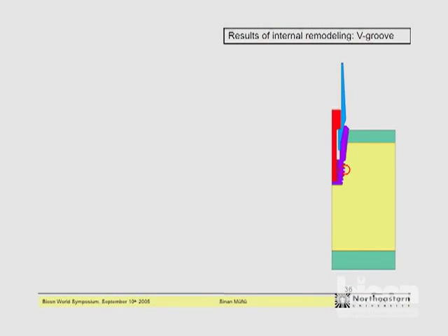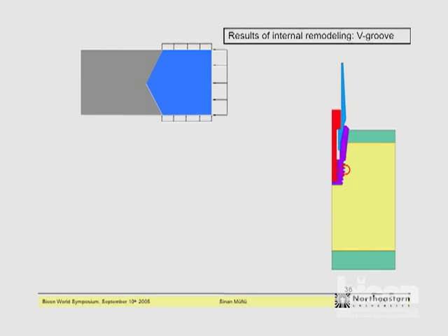And this is all thrown into a complicated finite element program. I'm not going to go into the details of that. But first, I'm going to look at the results of this type of bone regeneration model around a V-shaped groove that you may find in a situation like this. So the model starts with, this is the titanium part. This is a V-shaped groove. It starts with cancellous bone all around it. It's loaded radially and axially. So this is the radial direction, this is the axial direction.